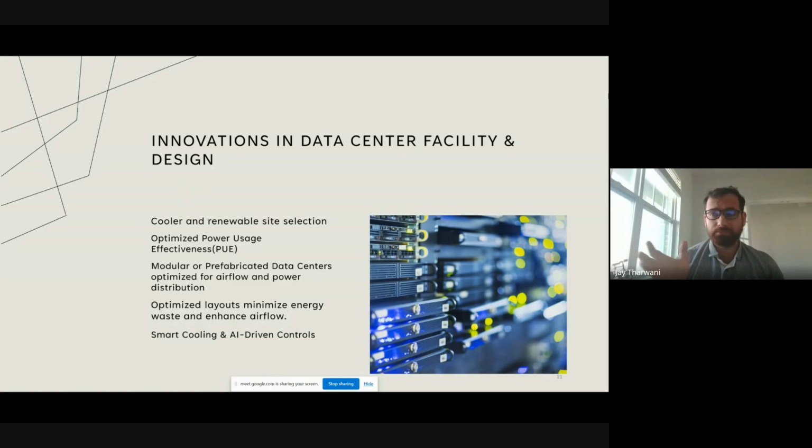Now you have data centers which have this ratio at 2. So basically the amount of energy taken by the IT equipment is half of what is being used in the entire site, which includes the IT equipment too. When people used to operate their own data centers, sometimes it was close to 2, but these hyperscalers like AWS and Azure have reduced this metric to 1.1.